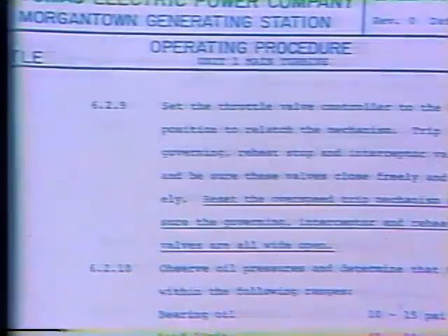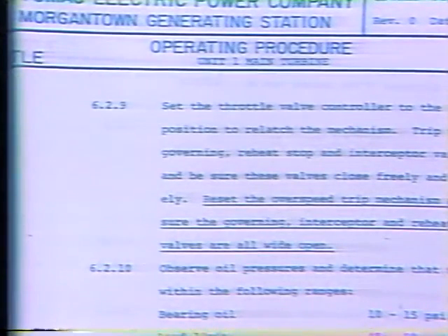All prints will have the information we just covered: the manufacturer or the name of the plant, the name of the system, machine, or parts, the date the print was drafted, and the print number. After checking the information block, get out the manufacturer's manual for the machine, or the system description if the print is of a system. The manual or the system description should have sections that will take you through the operation that the print represents.